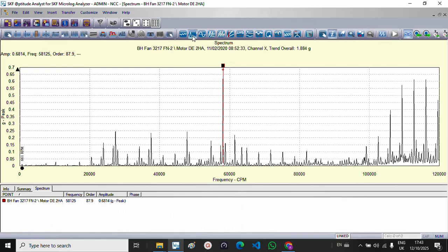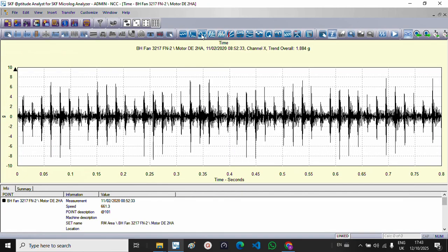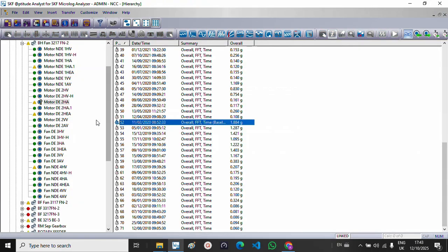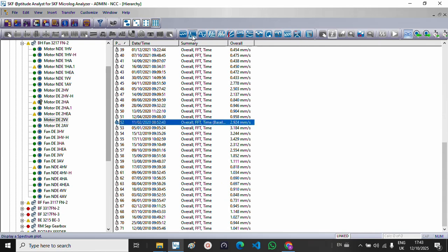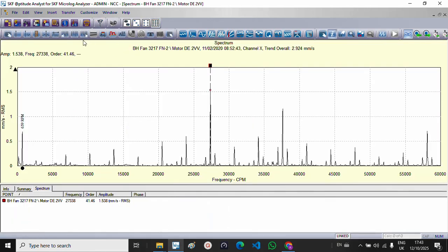We see the properties, the features of the spectrum, the features of the time wave, and oh, we see here more impacts in the time wave. Therefore we can concentrate on them. We will see here in the vertical point how the bearing frequencies are.